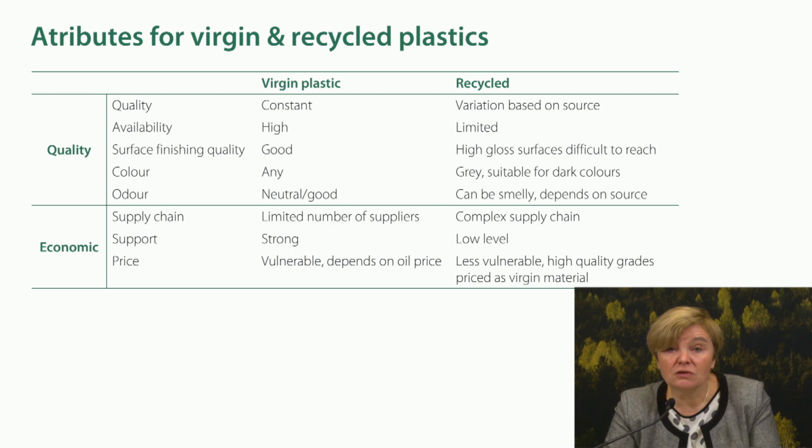And then one of the restrictions with the recycled plastic is actually the availability in the market. There are not many databases from where you can see directly the same property polymers. So it means that every company who is doing the recycling, they are selling probably their products already early enough at the developing stage, so you don't have necessarily easy access to the material.